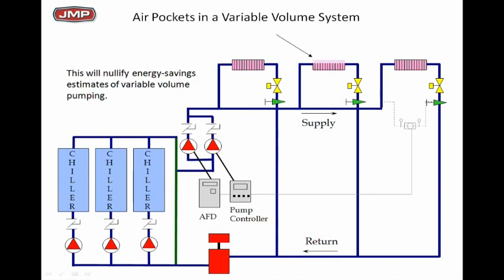air pockets get into the cooling coils, look at that center cooling coil. It's got an air pocket at the top of it, okay? We got a two-way valve on it. What does that mean? Stop and think a little bit. An air pocket is going to cost you money by your pump running faster.